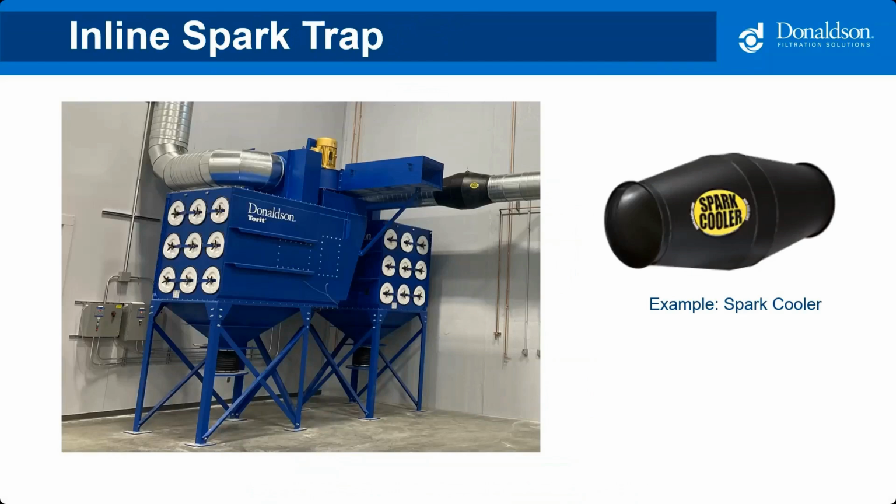Another option would be an inline spark trap, which would be located within the air intake duct, as you can see from this picture. In the image, you actually see two DFE cartridge collectors sitting next to each other, and then the one on the right has a spark cooler, which is the black piece in the ductwork. And essentially what that does is it creates turbulence in the airstream that cools and arrests most sparks without the use of water or chemicals. So let me show you a quick video on the next slide, and you can see how it works.